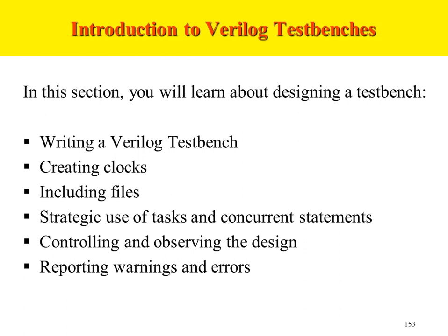The board, according to its circuit, processes those inputs and generates some outputs. You monitor the inputs and the outputs. You already know the logic of your board, so you analyze whether, based on the current set of inputs, the outputs generated are correct or not. Based on that, you say either my board is working correctly or there is a problem with the board.